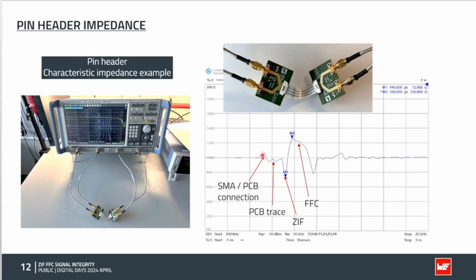You see that there is a small impedance change. These are good connectors, but it is not possible to have strictly no impedance mismatch here, simply because you are in a perfect coax round, and here you go into a more 2D, two dimensions medium. So you have a change in the geometry, so in the capacitance, so in the characteristic impedance. And also here you have the PCB traces that are not purely 50 ohm, well 100 ohm in that case, due to the FR4, the glass fiber, to some kind of parameters that you cannot avoid.